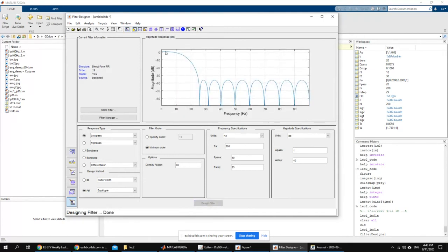And basically, it's going to give you the response of the filter that looks like this, okay? If you see here, you have almost all parts of the stop band after 25. It's basically around or less than 40 decibels. The range here that you're interested in is very close to 0. 0 is basically 1 because 20 log 1 is 0. So basically, here in the pass band, it's almost 1 everywhere. Okay, so basically this is the filter that we generated.